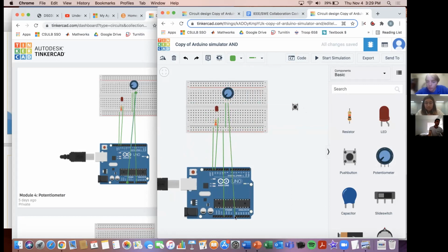So what you read from the potentiometer, what it's going to give out, so what value of resistance. And my pin here on the very right is going to be the voltage source pin. So I'm just going to connect it here to the 5 volt because these are all interconnected. And so I connected the pins correctly. So going again, on the very left, it's the ground pin. On the middle is the output, and on the right is the power supply pin.